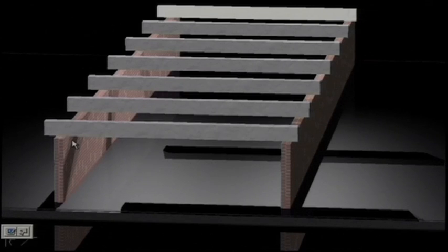We can take this beam as a simply supported one, because it is just simply supported over the masonry walls. There is no moment developed here, but when we take care of columns, that time moment will be developed. So, for frame structures the moment will be developed at the supports, but in this case you will have only simply supported. If it happens that one side is column and one side masonry, then you have to take care as propped cantilever.